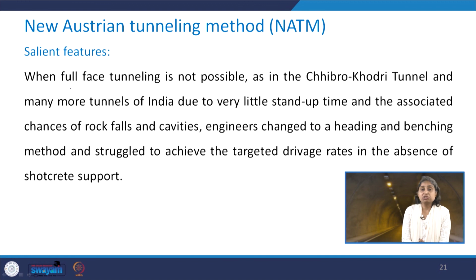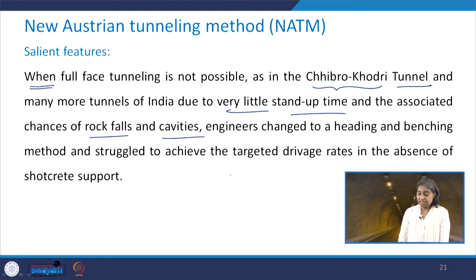As I mentioned, in all types of rock mass, full face tunneling may not be possible. This is seen in many of the tunnel construction projects in India, and one name I have mentioned here is the Chibro Khodri tunnel, because of the rock mass quality and hence very little stand up time. In that case, there are chances of rock falls and cavities.